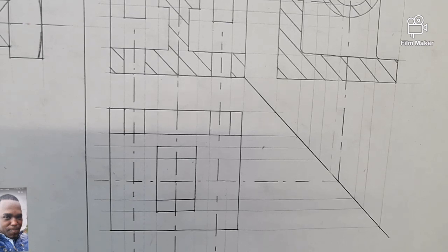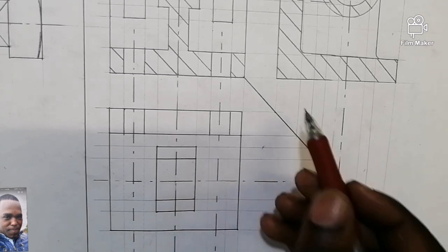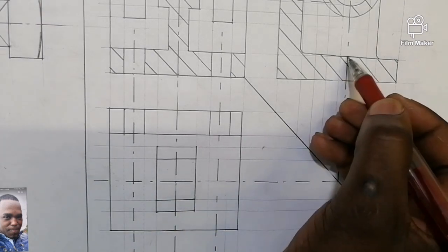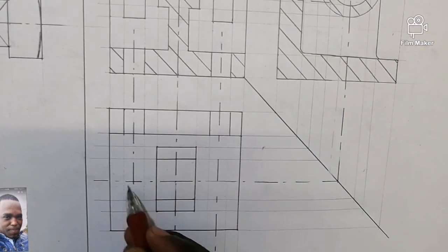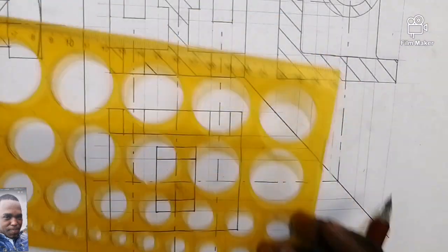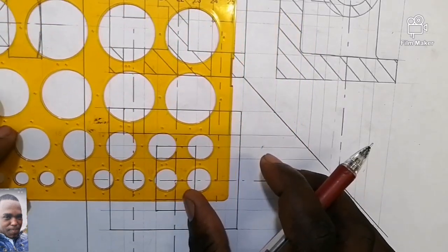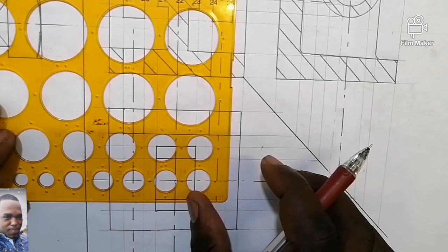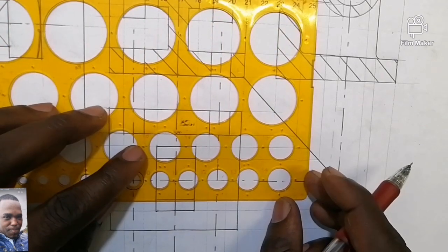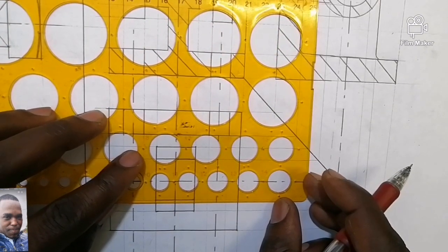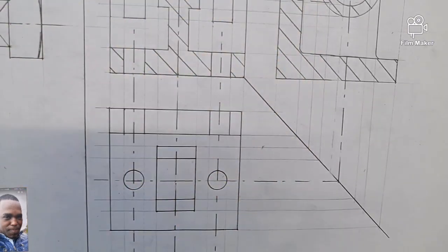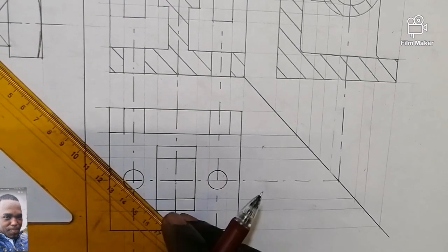What's going to be left? We are going to have holes where, remember that there were holes diameter 12 where, yeah, that goes. So which means we must have diameter 12 here, diameter 12 here. You are going to see it well now, like this. And right here. Then you can put your hatches. So what's going to be in sectioning is this.